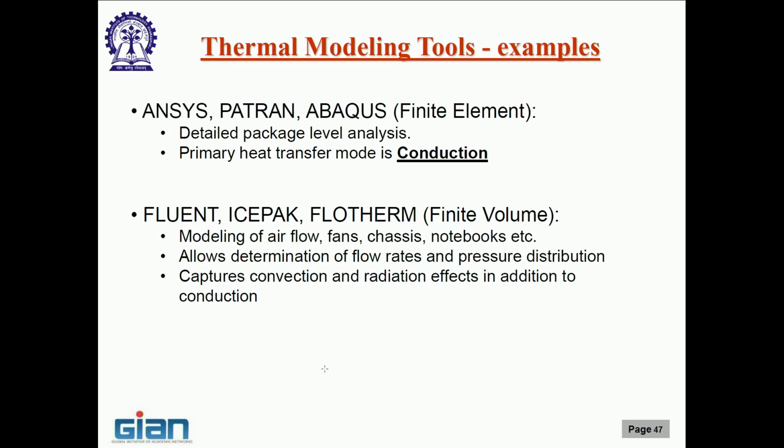So the ANSYS, Abaqus, Patran, what you are talking about, you can use only if the boundary condition is a convection coefficient. Okay. So if it's just conduction that you are trying to do, you can use them. If you want to look at flow, then the regular ANSYS that we know about, the finite element, even though now Fluent is also called ANSYS Fluent because ANSYS bought over Fluent, any of these traditional finite element softwares you cannot use to model flow or solve flow equations. So therefore you cannot get pressure, velocity, all that information.